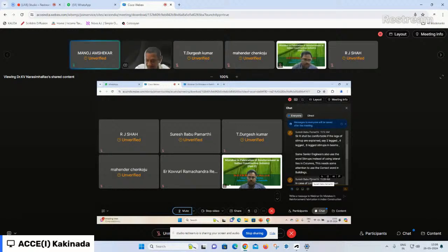Okay, sir. Sir, in the case of Ld/3, it is just an anchoring length, not fixity. Yeah, just the minimum anchorage length from the point of view of continuity of the bar without any fixity, sir. Beyond Ld/3 to full development length, partial fixity; up to full Ld, you have the fixed condition.